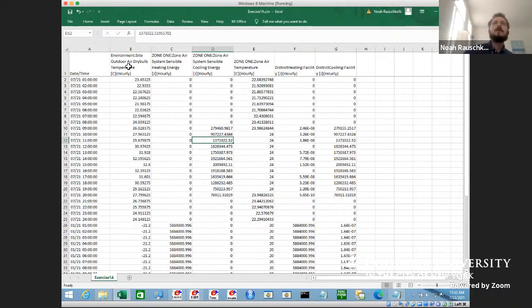So yeah, the room temperature gets up to 24, and now your air conditioning system kicks in. And then once the temperature drops back down to 23, and this is going to be at 8 p.m., so it's got back down to 23 or just below 24. The sun has set, so you don't have those strong solar gains anymore. And even though it's a little bit warmer outside, the building is starting to cool off.